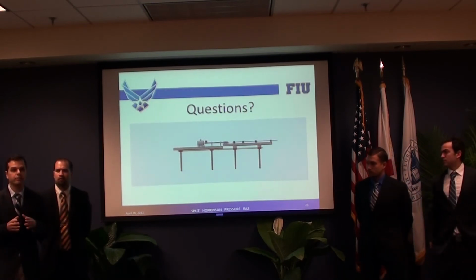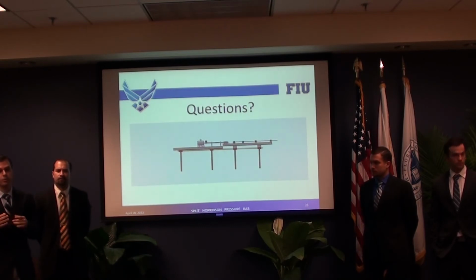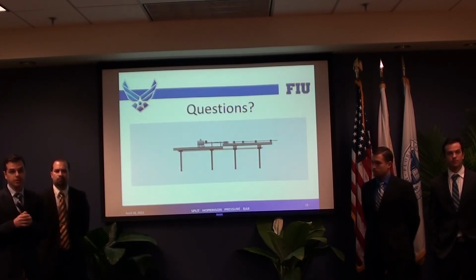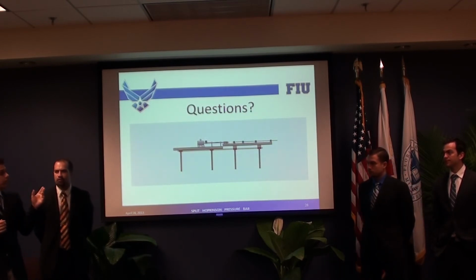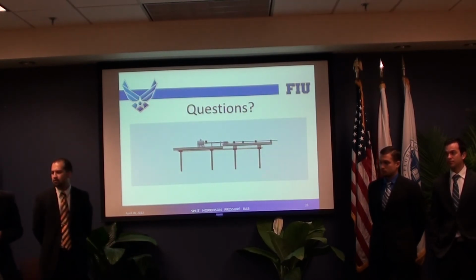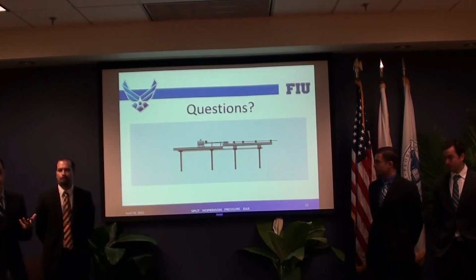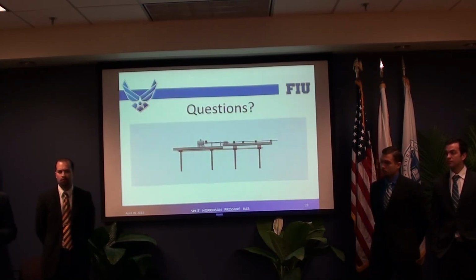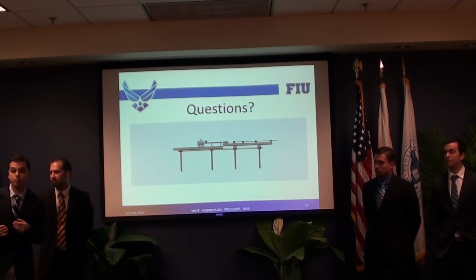In textbooks we've read that for a minimum you need a 100 kilohertz data acquisition system. Now when you find the frequency of that, you're going to get about 8 microseconds time period per point. Our stress pulse turned out to be 83 microseconds, so the length of this square wave is 83 microseconds. If we were to use a 100 kilohertz time base, we would be able to get approximately 8 points in this square wave. Now this oscillation effect is known as the Pochhammer-Chree effect.